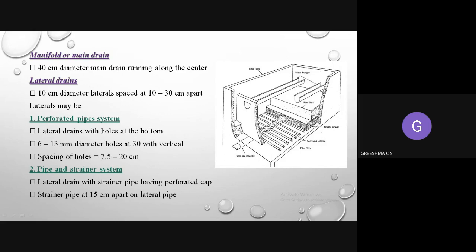Okay, the caps are provided here. Okay, with strainer pipe or cap provided now. And this strainer pipe will be at a 15 centimeter apart the lateral pipe. You can see it as an extension of this lateral pipe.